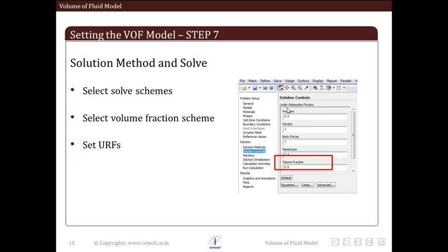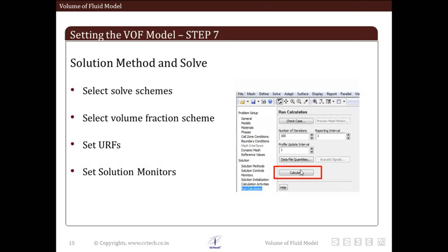Then we set the URFs, that is the under relaxation factors. After this we set the monitors, that is the parameters that we want to monitor while the calculations are running. And lastly we click on calculate in order to start our solution. So this completes the setup of the VOF model.